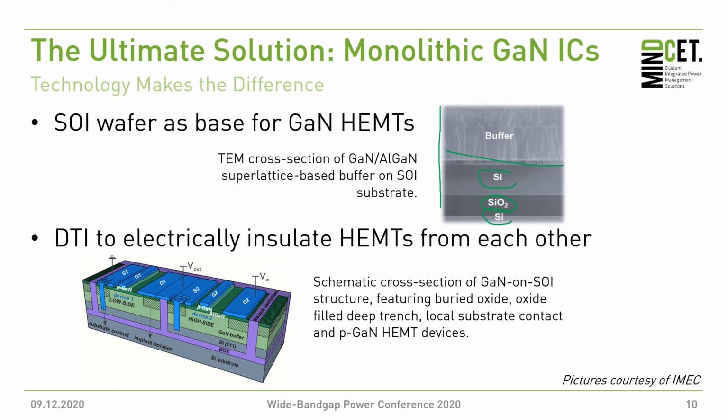So this silicon dioxide layer, the glass layer here, in addition with deep trench isolation, allows to create boxes, glass pockets that are able to really physically separate one GaN HEMT from another in a galvanic way. And this brings a possibility to make true floating half bridges and true floating circuitry.